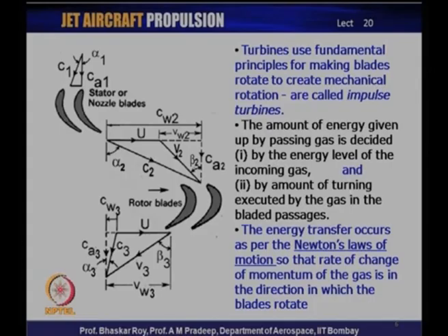And the flow coming out here is V3. The C3 here is again purely subsonic. The flow normally is kept subsonic through the turbines, essentially as I mentioned, to avoid shocks. And remember, if you have a multi-stage turbine, as we shall see later on, this flow is going into the next turbine again with a lot of potential energy, and hence it is necessary that you try to keep the losses down, because shocks are associated with losses.